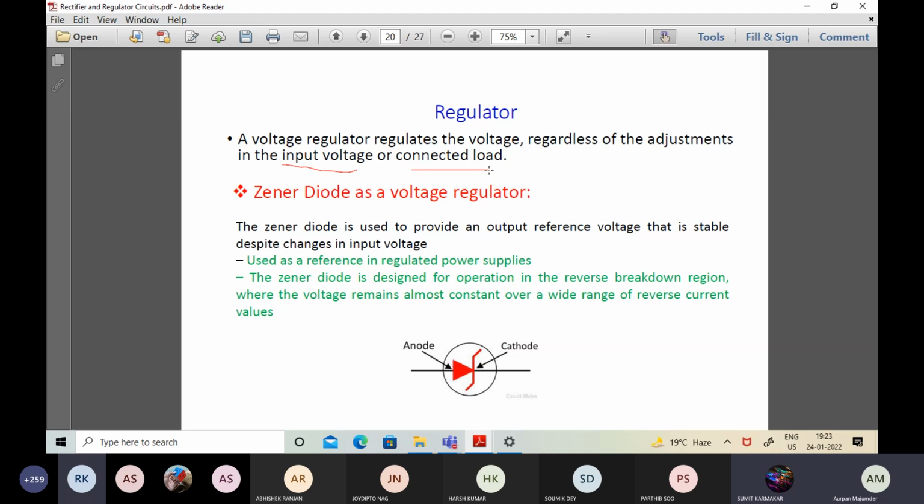It is basically a PN junction diode only, but the concentration level of the dopants is pretty high compared to a normal diode. Owing to this, the barrier height or the barrier potential is quite low, and because of that, quantum mechanical tunneling of electrons comes into the context.